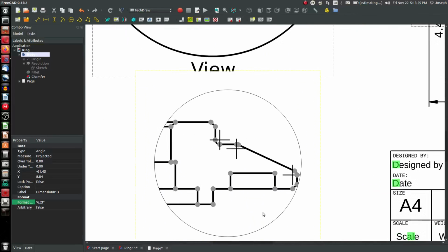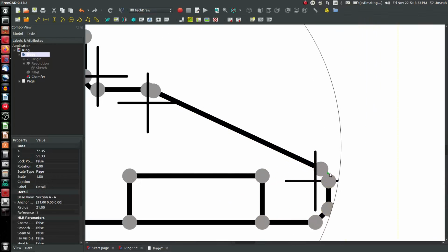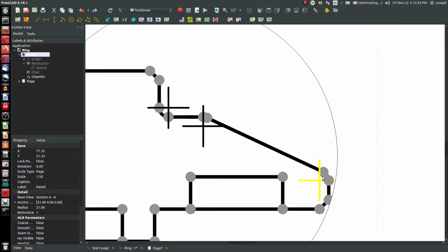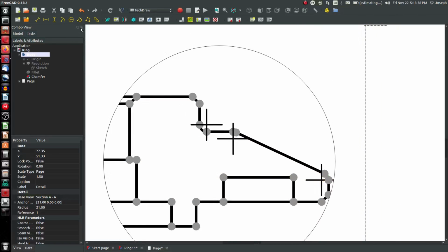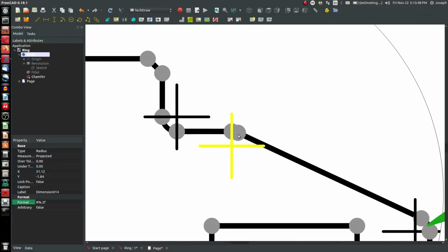I might want to go down to my detail view now and start choosing something like a radius value. If I choose that radius behind those points, you can hardly see it with the points turned on. And there's my radius symbol there. Notice I can insert a little radius, however I think is best. Now, I have the same radius here and here.